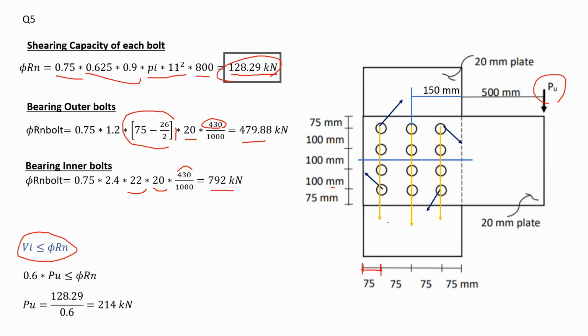Because the shearing effect is in the X and the Y direction. So actually that bolt might come out from here, or it might come out from there. Or it might even go to the next bolt. That's the tear out distance that might happen. So you would pick the least clear distance. You're welcome. Any more questions, guys?